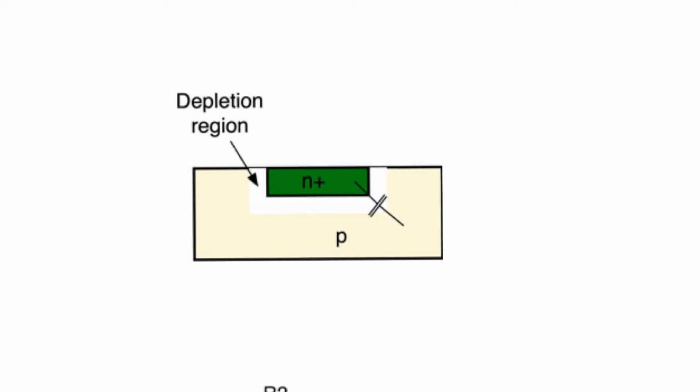So now let's talk about resistive wires. That is, wires that have a resistance that is appreciable as well as capacitance. In this case, we are usually talking about polysilicon wires or wires created in the diffusion layer. First, let's talk about the diffusion layer because it has a little bit of a specific curiosity about its capacitance.